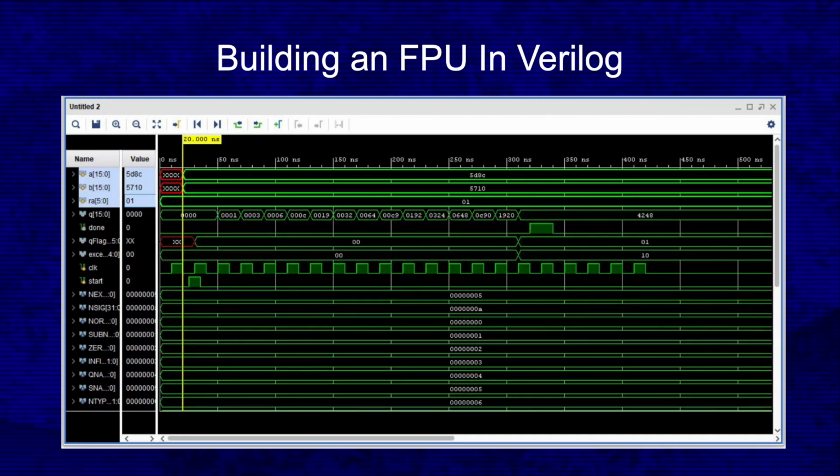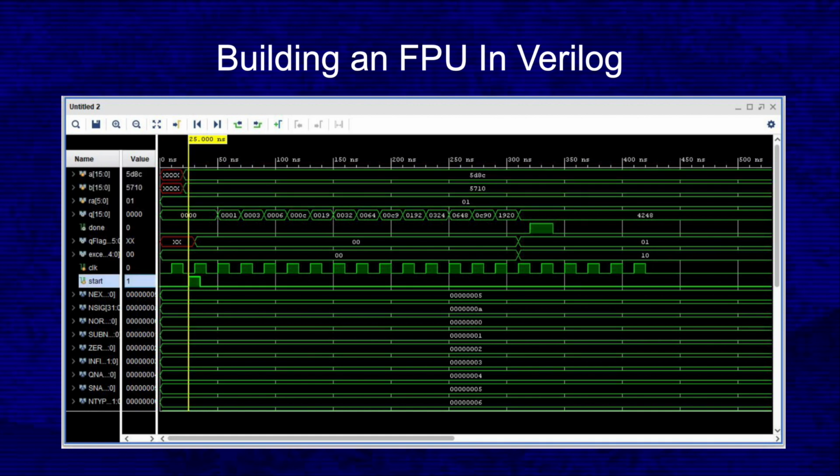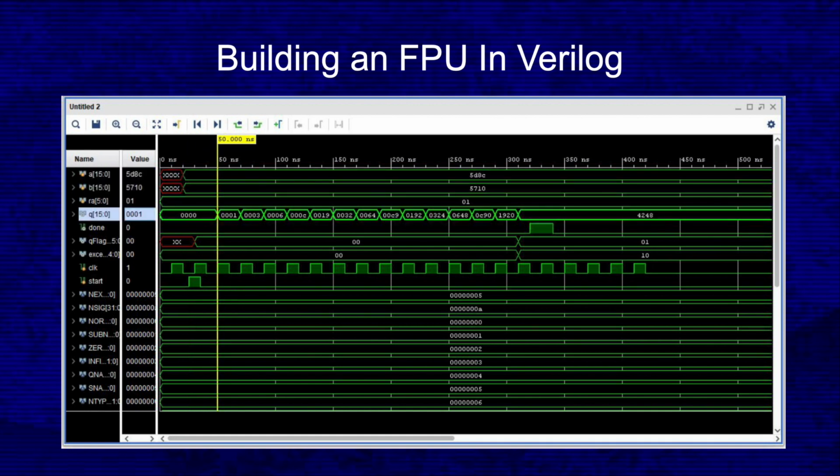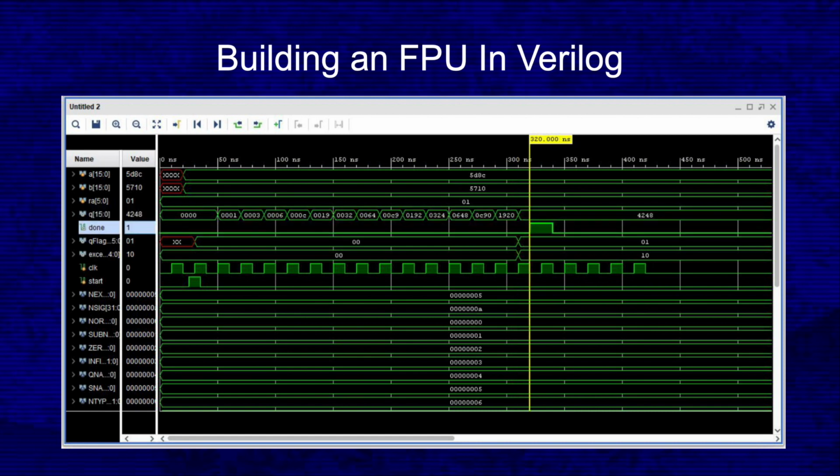This trace is for the case in which the division circuit needs to perform long division. Again, the dividend, divisor, and rounding mode inputs are presented, followed by a pulse of the start signal. Each cycle, the module exports Q to the outside world for diagnostic and didactic purposes. That is, as each new bit of the quotient significand is computed, we can watch its progress. In the last cycle, the circuit finally constructs the final return value, and again, like the exceptional cases, asserts the done signal for 1 clock cycle.